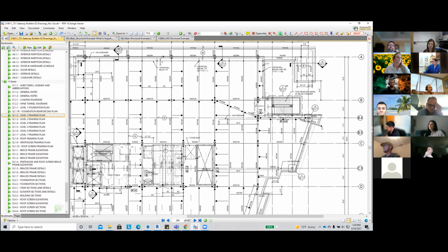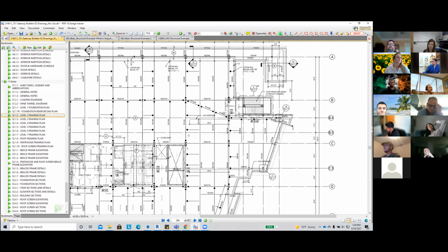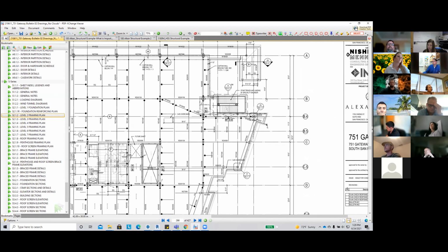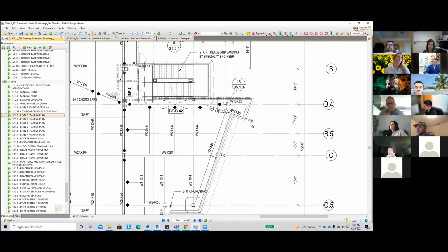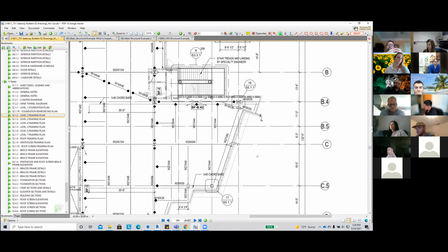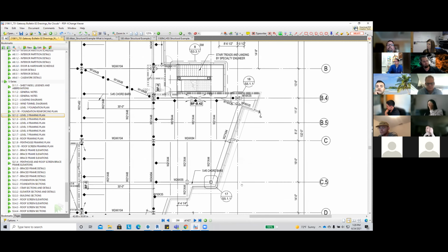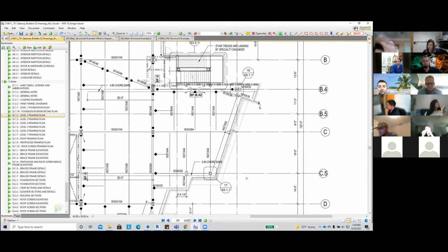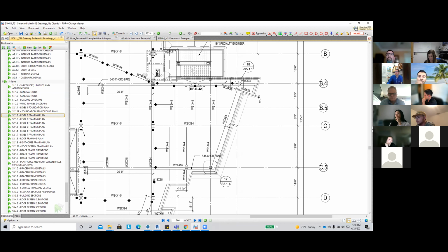So for example, you're talking about this direction, the horizontal direction. In this case, you're given most of these dimensions, like, for example, here, 11'3", then 8'3" for this. And then you just have the weird one sometimes. Does anybody know, is that assumed? Typically, I don't think it would be assumed, because if you look at that oblique corner right there, you have a grid line dimension, but you've got those W21 by 44s that are not evenly spaced. Yep, that's a great example. If that impacts you and you need to know, that would just be an RFI.